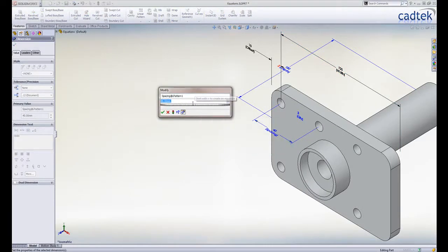By typing the equal sign, SolidWorks starts building the equation, and even colours the equation to let us know if the syntax is correct. In this case, we want to build an equation that solves the overall length and determines the hole spacing of these three holes at the top of our part.